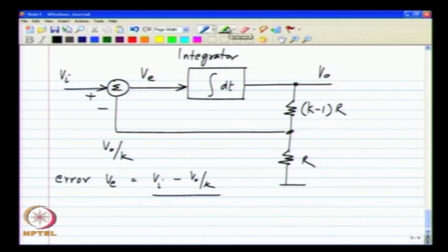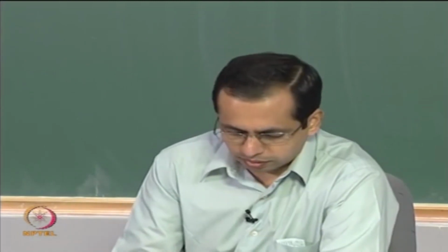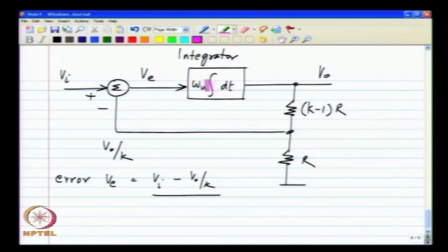First we look at the integrator. If you look at this integrator, it has a voltage output and a voltage input. So, for dimensional consistency there has to be a constant here which has dimensions of frequency. We will examine the integrator in detail, it will be clear what the role of this constant is. But before the integration you need to have a constant which has dimensions of frequency.